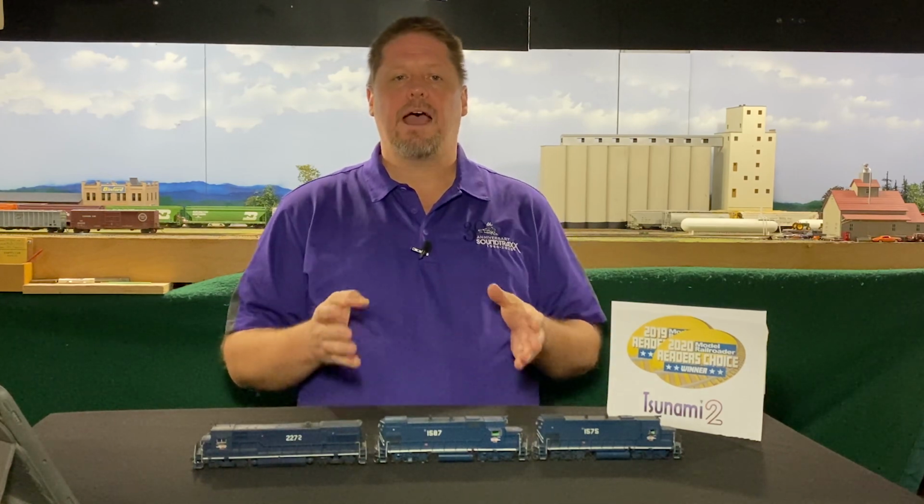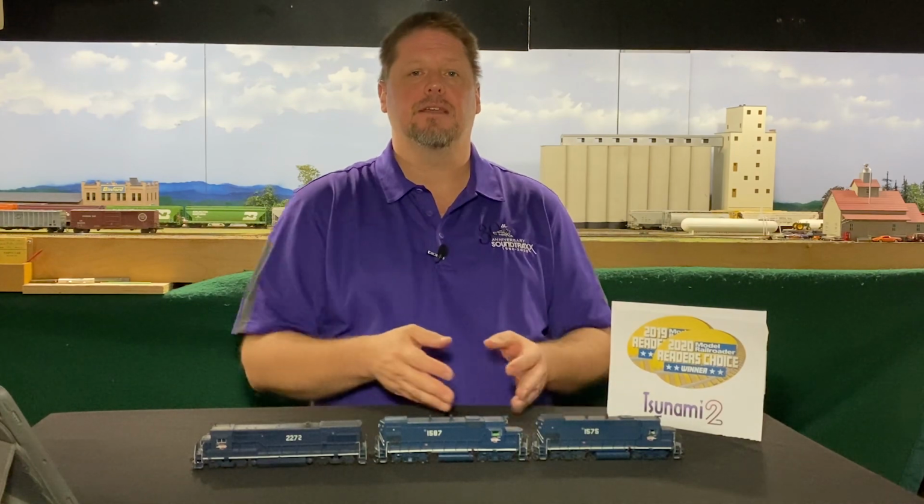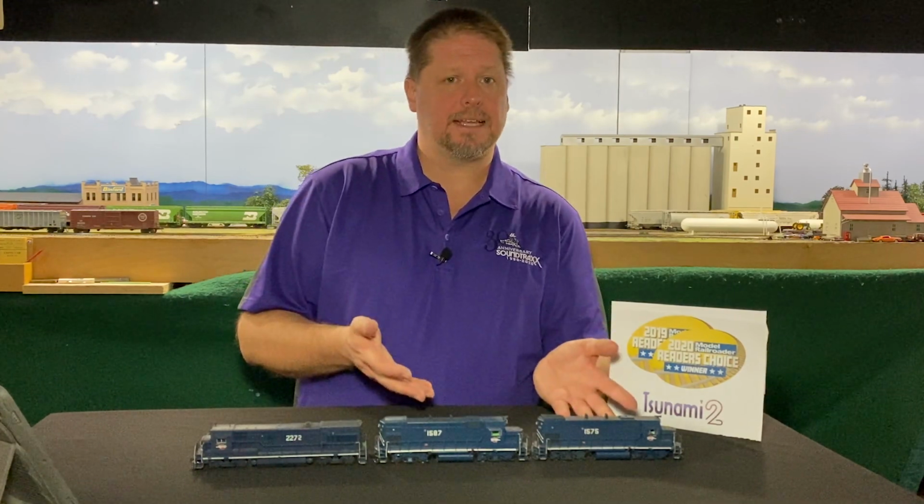Because when your basic consist, or what I've heard is called universal consisting, is stored in your DCC memory, it knows which one is the lead, and so it sends all the function commands to it. Keep in mind, when these were developed, we didn't have sound decoders, so the only thing that was pertinent was the lights. And so that's why this design is done this way. So the lights would be on the lead unit, which would be correct.